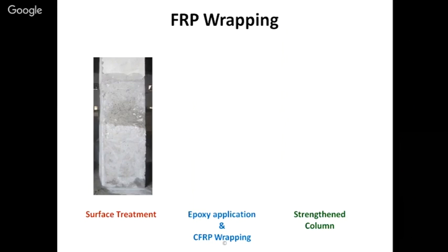That's why we have applied a special epoxy on the old surface. Then we used a letterbox shuttering line. This shuttering is generally referred to as letterbox shuttering. So when you fill concrete and lock like this, that will give you additional pressure. Now the concrete will touch the topmost surface, which is already applied with epoxy. So now the possibility of shrinkage cracks can be avoided or eliminated. So this is a retrofitted column. The bottom portion is new, and the topmost column is old concrete. You can't see any connection.